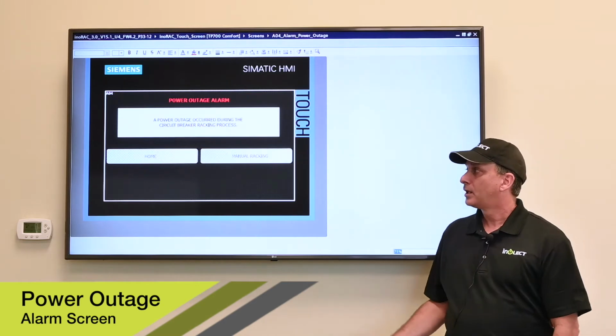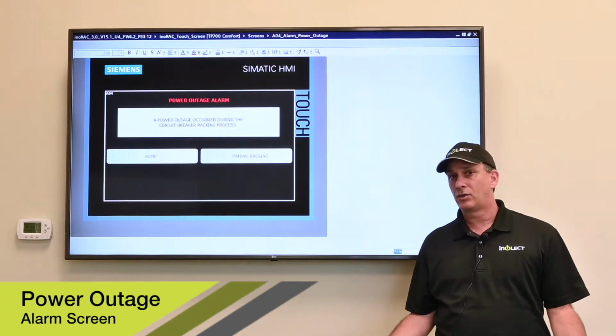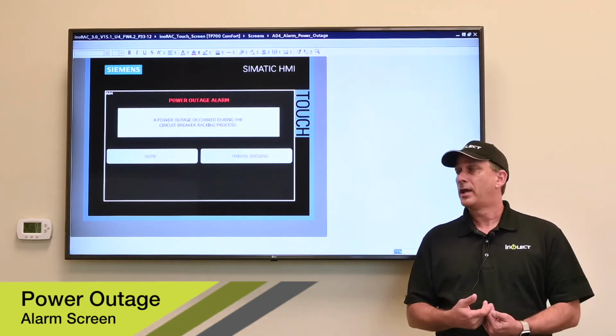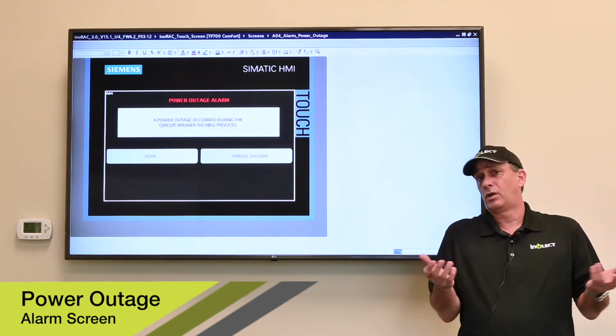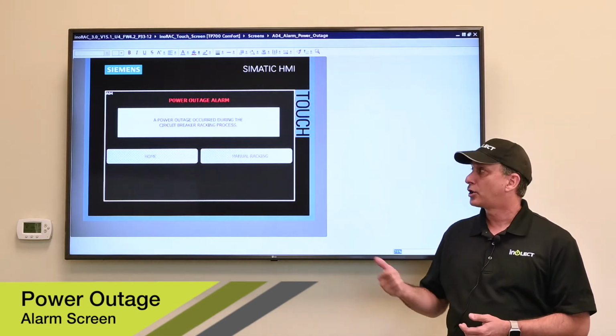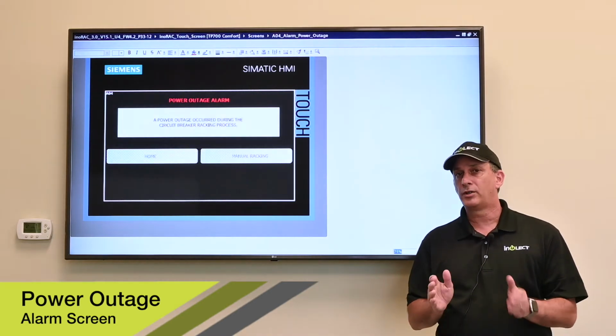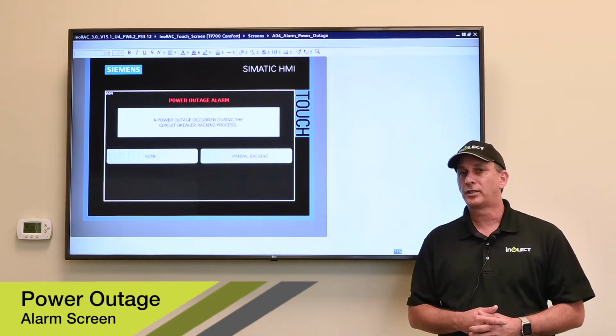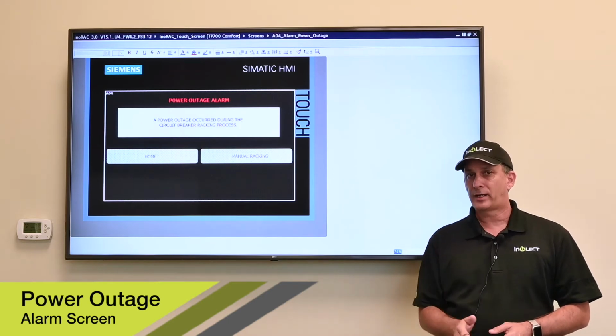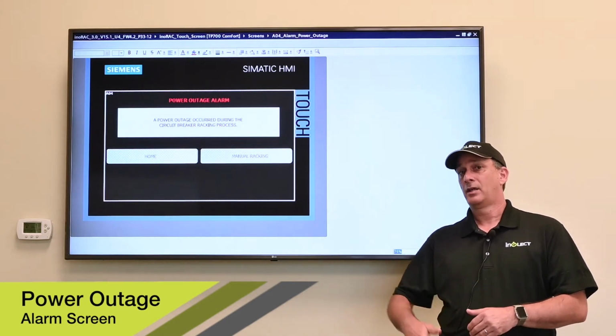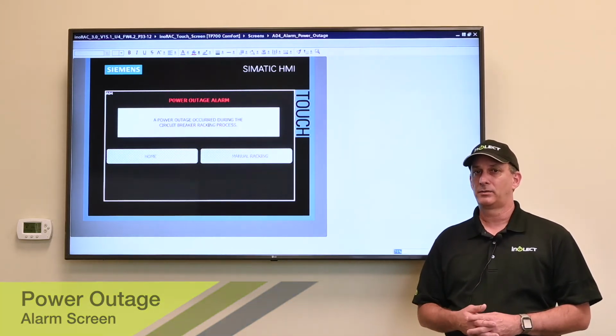If you ever come to use the racking unit after any of your coworkers have been doing energy isolation or racking breakers, you turn the racking unit on, and if you see this screen, whatever breaker you're getting ready to rack, you just want to double check that that breaker is completely racked in the connect or disconnect position.